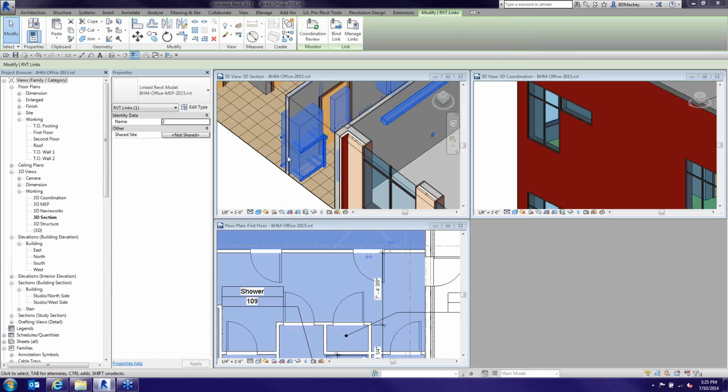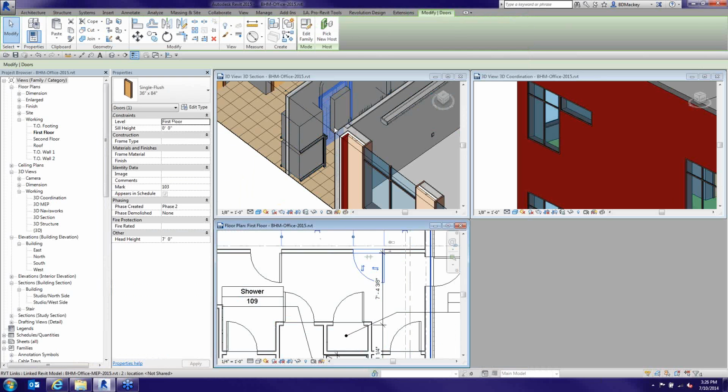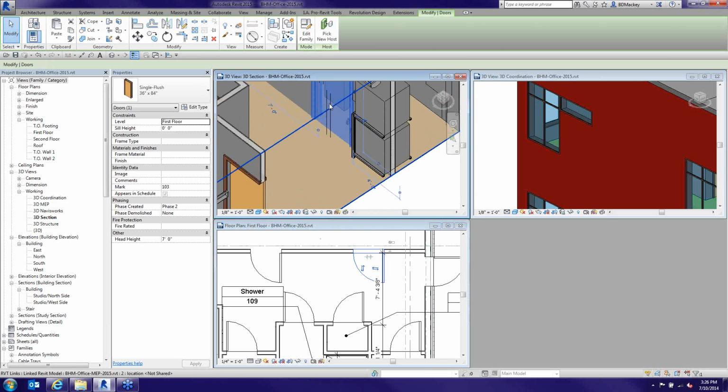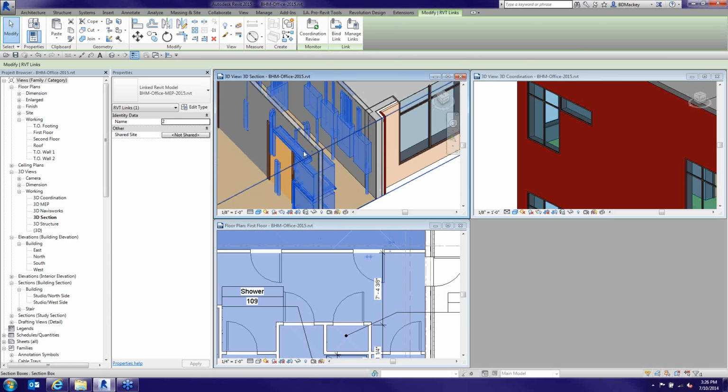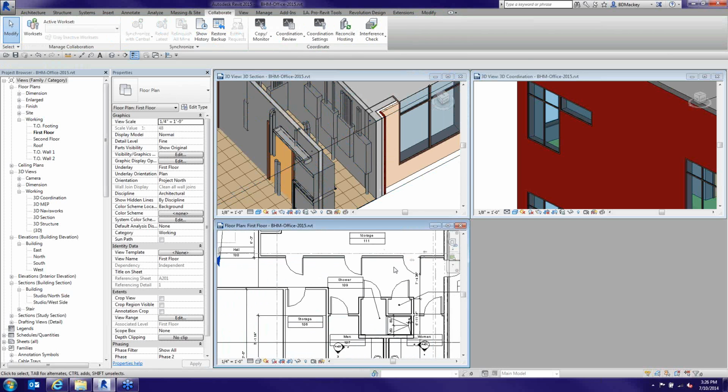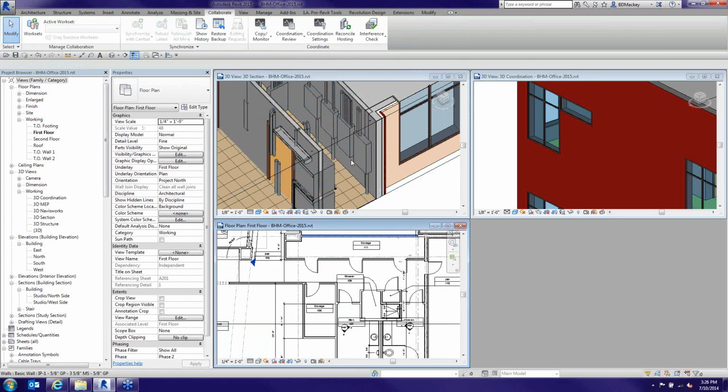Pay attention. Right? So trying to isolate this, seeing what's going on with this door really is going to let me know, oh, it's this. And not only is there a panel there, I think if I spin this model around slightly, this might be some conduit going up, and there could be conduit right there. So okay, something drastically changed here. And I might not have noticed this looking at it in a floor plan view. Yeah, I can see there's some conduit here if I'm really paying attention. So it looks to me like I moved this wall for the storage, and I've just now completely hosed MEP. Well, shame on you.